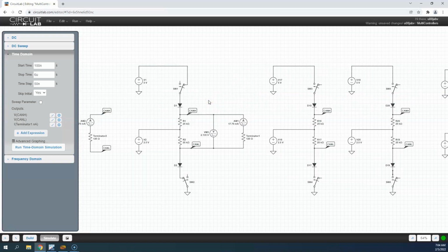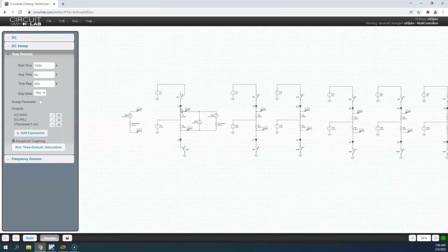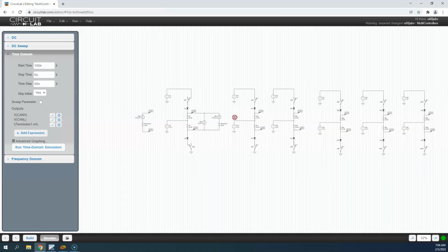The transmitting controller has to listen during the acknowledge bit period. When the acknowledge bit is being transmitted by the other controllers, the controller which transmitted the message, which is being judged by the other controllers, has to listen to see if the other controllers are okay with the message. So this is one rare instance in J1939 and CAN where more than one controller is going to transmit at the same time. The other being, of course, arbitration, when the bus is idle and several controllers start transmitting at the same time. It's a similar phenomenon.